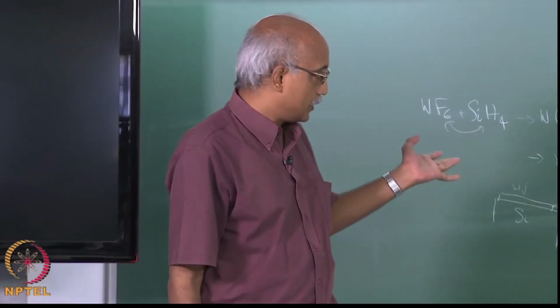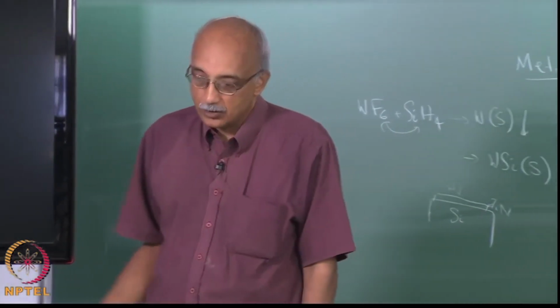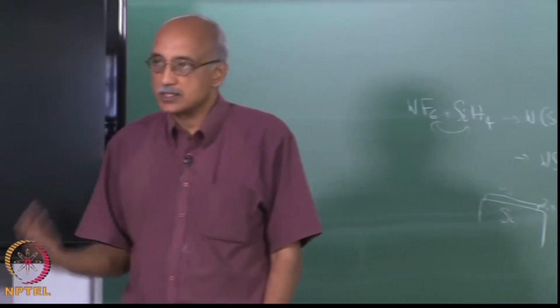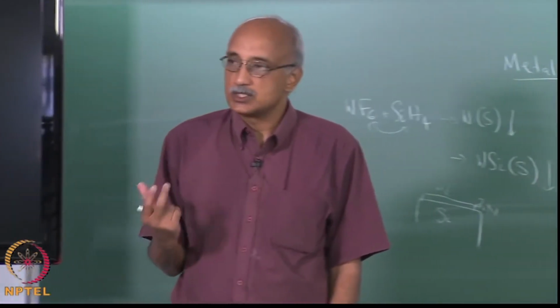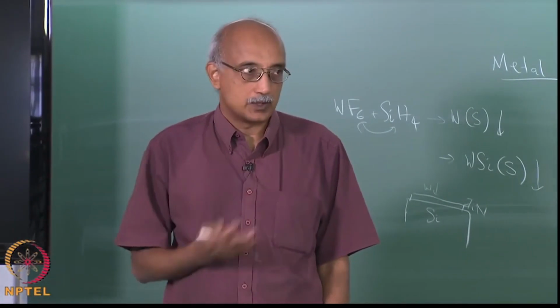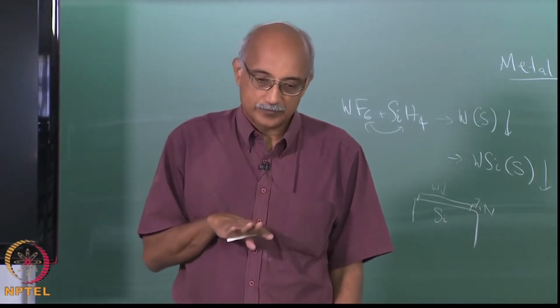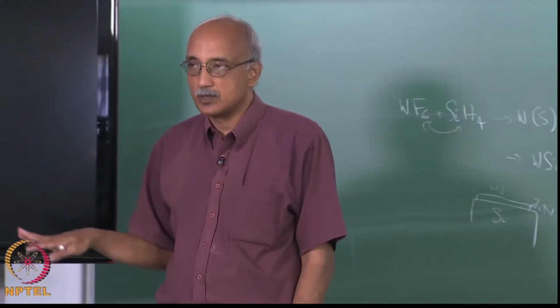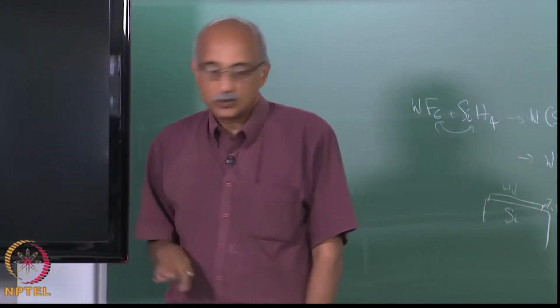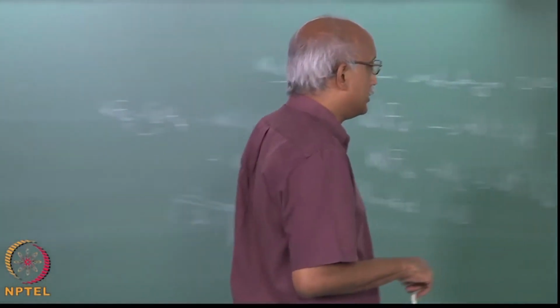Unlike, for example, tungsten, where there are both inorganic as well as organic vapor species that can be used to promote the deposition process. So, if you want to use CVD to make a layer of copper, you have to use what is known as MOCVD.